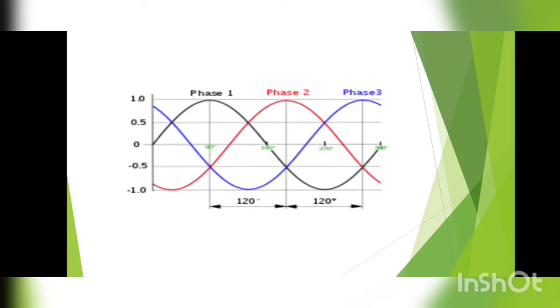The three-phase system has four wires: three current carrying conductors and one neutral. The cross-section area of the neutral conductor is half of the line wire. The current in the neutral wire is equal to the sum of the line currents of the three wires and consequently equal to square root 3 times the zero phase sequence component of current.